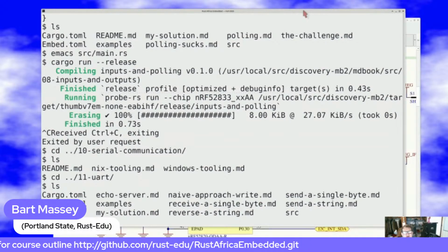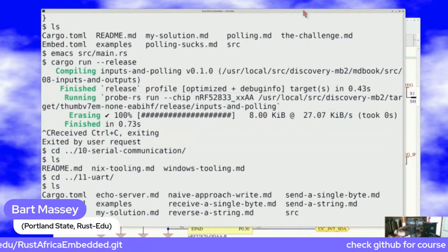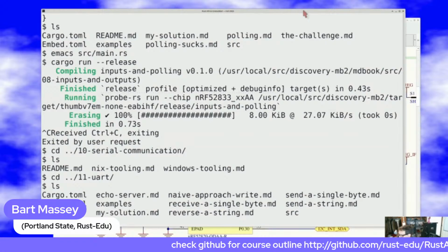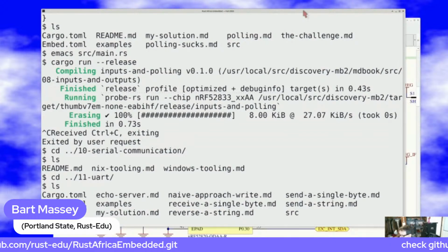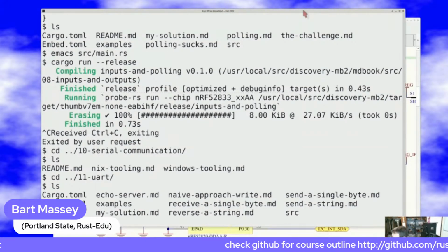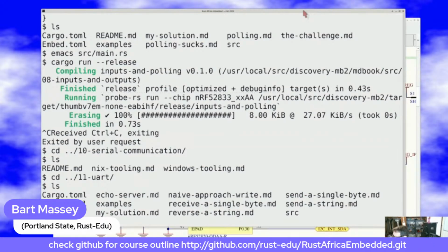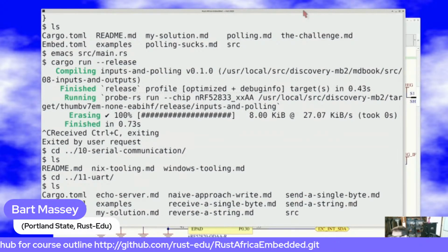That's all been replaced by USB, right? What you have on your computer is a USB connector. Well, that's also how we connected our micro:bit up, right? With a USB connector. So what we do is we use the serial port on our micro:bit's main computer to talk to the interface microcomputer, and then the interface microcomputer speaks USB to and from your host computer.